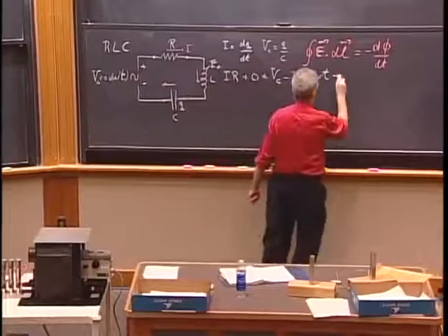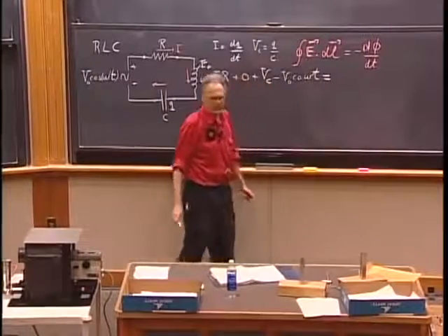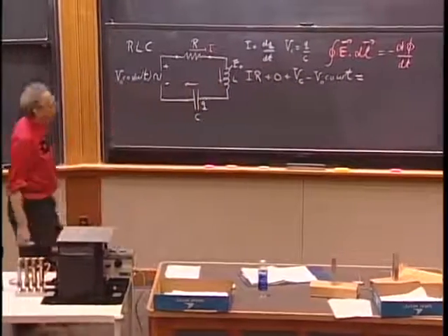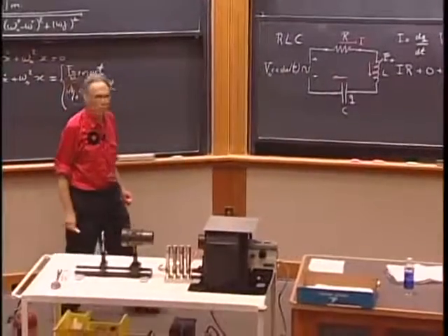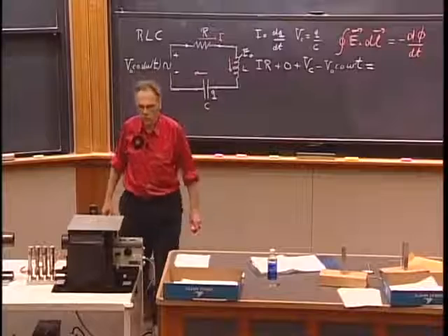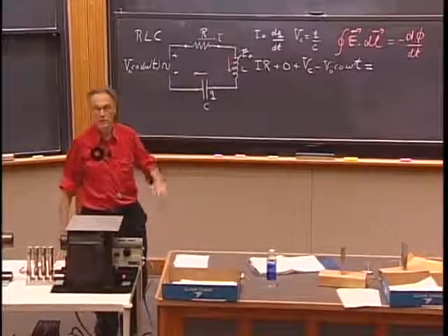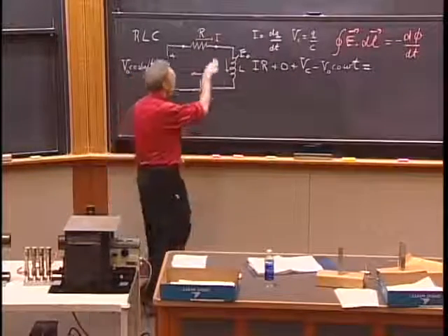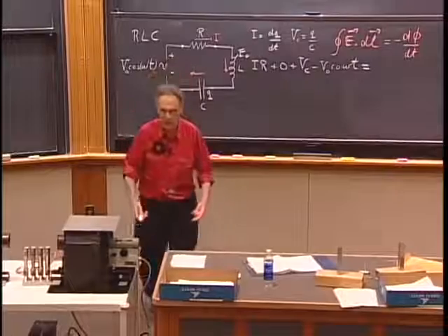And this now equals minus dΦ/dt. The only thing when you apply Faraday's law is you should always integrate in the direction that you have your current assumed. Then it is minus L di/dt. If you do it in the opposite direction, then it is plus L di/dt.